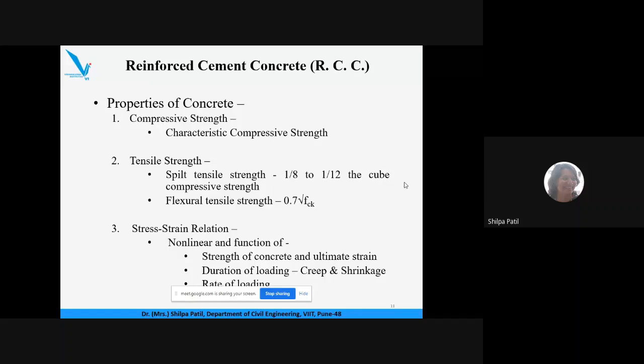This is because of the heterogeneous nature of concrete. The materials used for making concrete are all heterogeneous. Even though they have the same individual properties, we still get different values. That's why simply by conducting 1 test, 2 tests or 3 tests, we cannot find out the final compressive strength of a concrete or for a specific composition of a concrete.